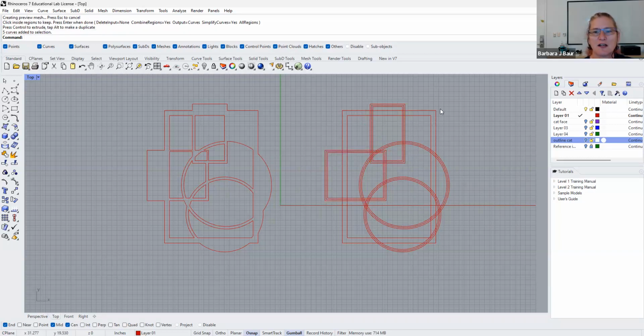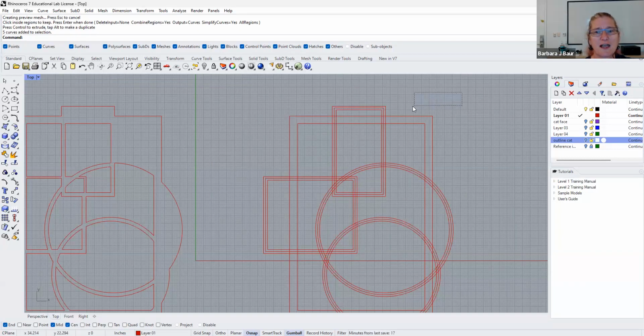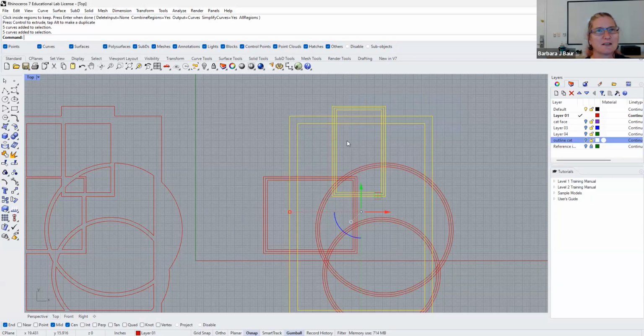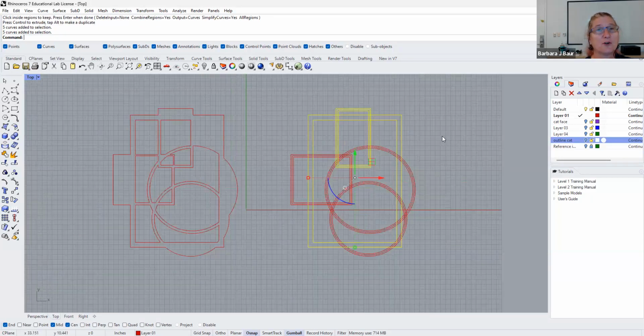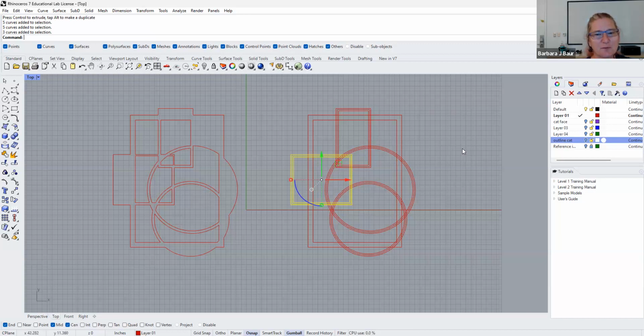Like, let's say, remember I was talking about the selection earlier, dragging left to right versus right to left. If I start on my right-hand side and drag towards the left, anything I touch will be selected. This is really powerful because now if I only want things, if I drag from left to right, then anything that is fully enclosed in there will be selected, but not everything I touch. I'll remind you guys of this. It's super useful when you start to get into really busy things.